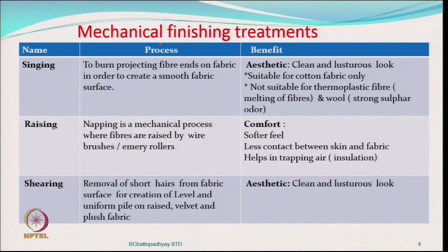By singeing treatments, we can get a very clean and lustrous look of the fabric. So, this is a very common treatment which is given to the cotton fabrics very well. So, generally they are suitable for cotton, not suitable for thermoplastic fibers, because there is a chance of fibers to melt because of the temperature. And it is also not suitable for woolen fabrics, because there is a strong sulfur odor which will be created. So, mostly it is applicable to cotton fabrics.